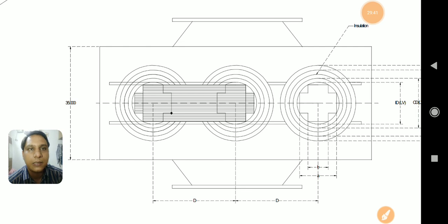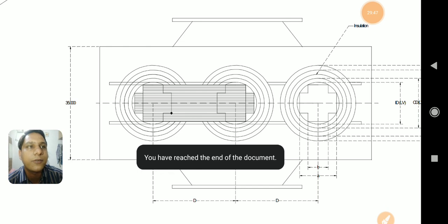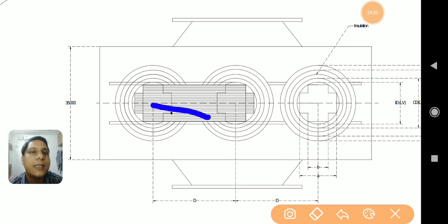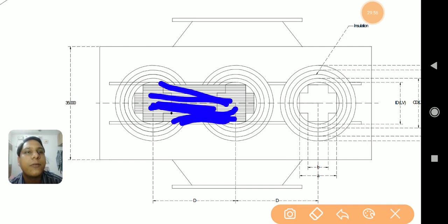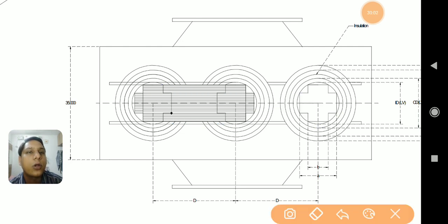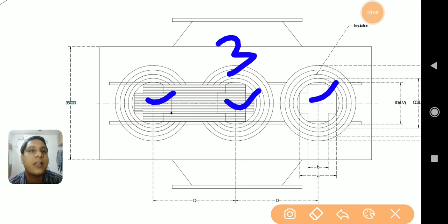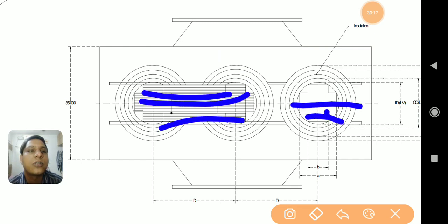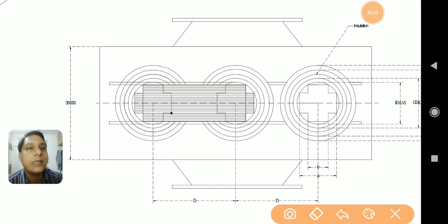Apart from that, if you look at the shape, you can find it interesting once again. What I'm going to tell you is really interesting. If you look at this shape, these lines are representing something which is not shown here. Actually, they have to be shown like this, because this is part of the same core. This is a core of the transformer. As it is a three-phase transformer, three cores are shown here. And if the representation of one core is like this, then these lines are also present. We need to understand, friends, this is a cut section of the top view.